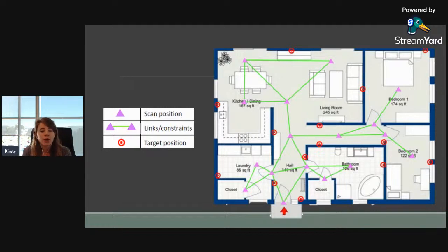So when it comes to doing the combined approach of tactical targets, I've got this diagram here from one of the Leica handouts. I'll find the link for that when these slides are sent around. What you can see here in this diagram that I really love is they've done loop closure as much as possible. And then in areas where there's less loop closure, they've got more targets. So if you look at the center of that diagram in the corridor there, there's a load of targets around those scans where there's only one link between them, those ones that I was calling hanging scans before. So what they've really done is added in a load of extra links there to strengthen that registration.